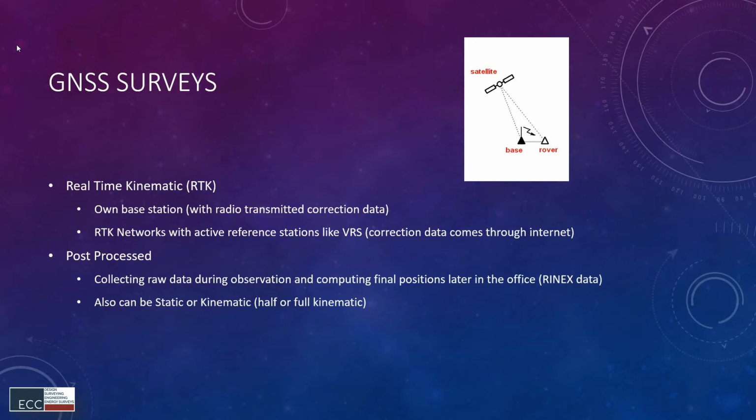Post-processing can actually be two different things. I didn't write it here, but we can do it if we still use the VRS network, just not in real time. We can set up our base in the morning on a not known point, anywhere, and just make sure it stays there, not moving.